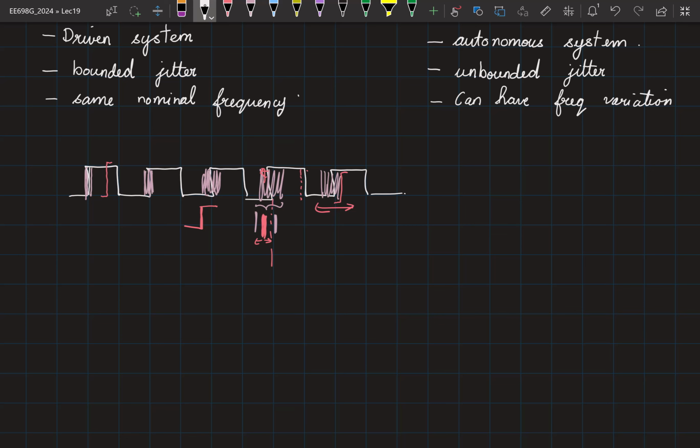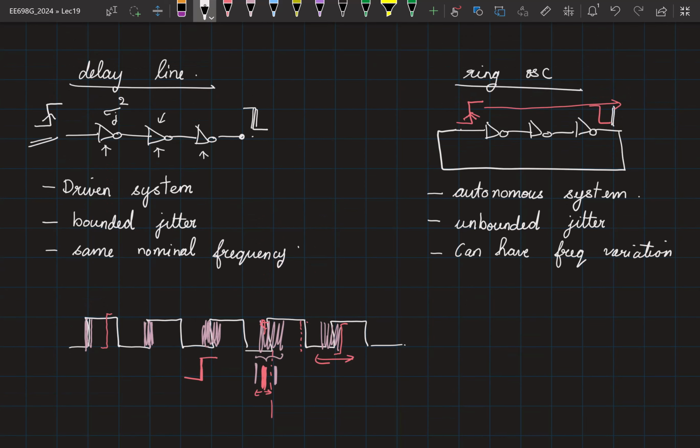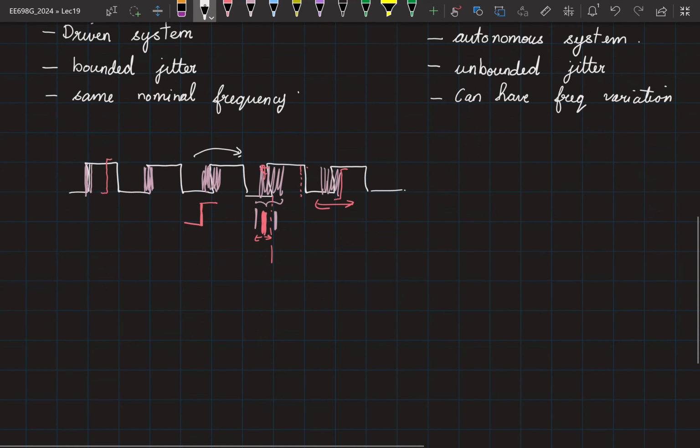Absolute jitter is going to blow up, right? Similarly, relative jitter is also going to blow up. Meaning, just an oscillator without putting it in any negative feedback. An oscillator like this, standing alone, lonely. Period can also change, right? So what will you compare it to? The cycle to cycle jitter, right? Because you don't expect to see a lot of jitter variation from one cycle to the other. So if you wanted to compare two oscillators, especially their jitter performance, and if they are standalone, then cycle to cycle jitter is one of the jitter metrics you can use.